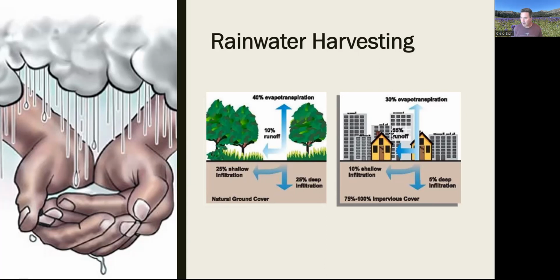This can be in the form of airborne heavy metal pollutants that are in our air and settle on our concrete and our roofs. And when water hits that, it goes into that water soluble, and then it flows into our storm drains, our creeks, our streams, our rivers. So we have a significant amount higher volume of water in our urban environments and significantly higher pollutant loads in that runoff. And we're going to talk about some strategies to reduce that in our urban environments.